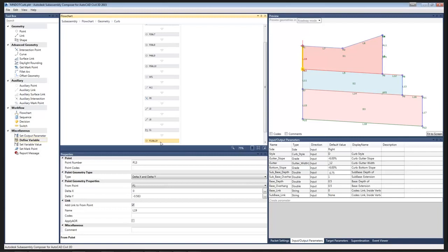That comes in handy when you're dealing with my sequences for defining the variables of the gutter width, face, pitch, depth. I copied the sequence and then just pasted everything in. And then all I had to do is do the quick change instead of saying create sequence and then set variable value 5 times with 4 variables in each. It saved me a lot of steps.